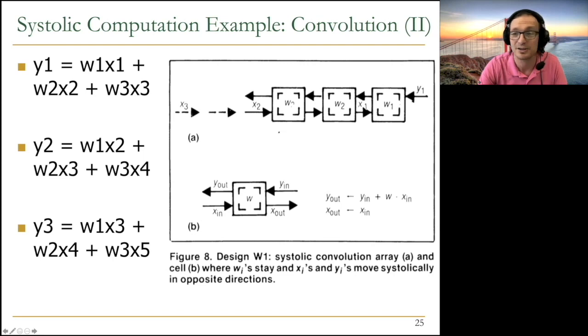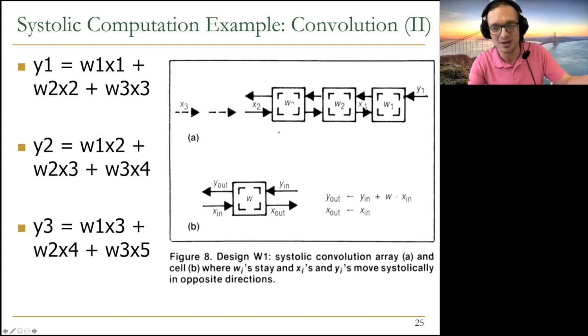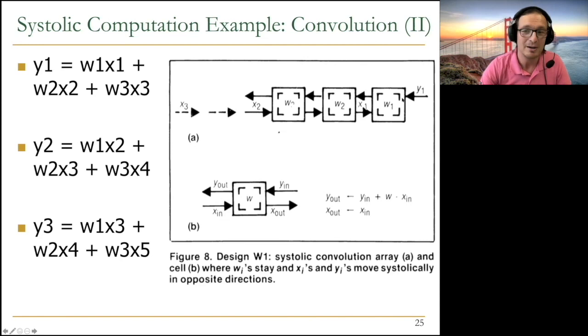I think so, yeah. So Y1 is equal to W1 X1. Okay, basically you accumulate things onto the Y1. Initially Y1 is 0. You should also assume that initially Y1 is provided as 0. But once Y1 goes here, X2 also arrives here. Basically Y1 also accumulates W2 X2. And once Y1 goes here, X3 also comes here, and then Y1 accumulates W3 X3. So basically at the end, when Y1 gets output over here, you get W1 X1 plus W2 X2 plus W3 X3 by just flowing the data through these processing elements that have different weights, W1, W2, W3.